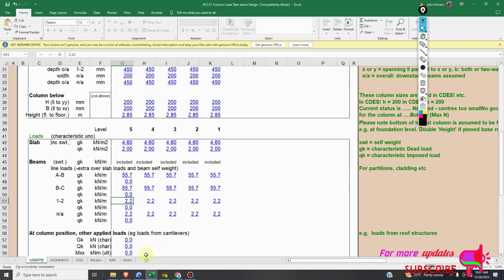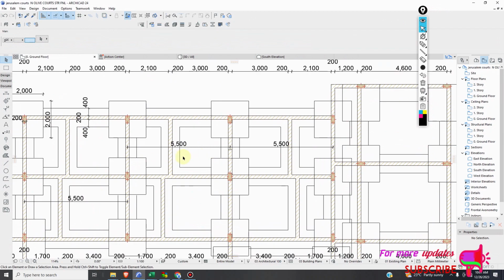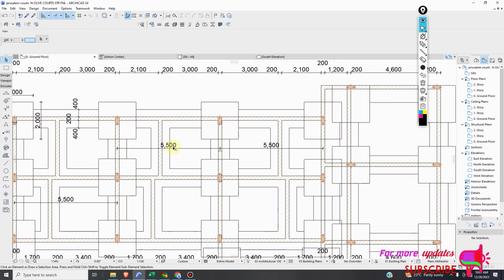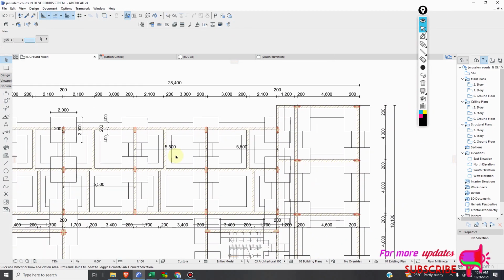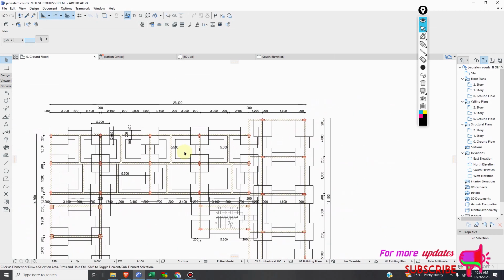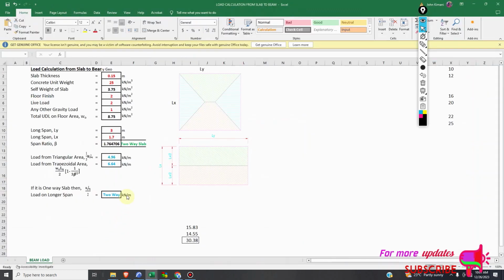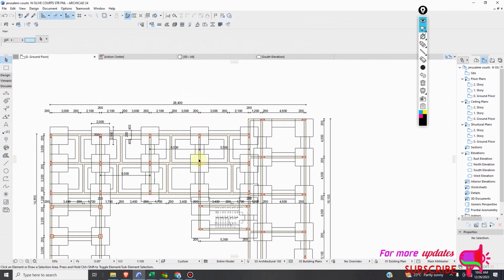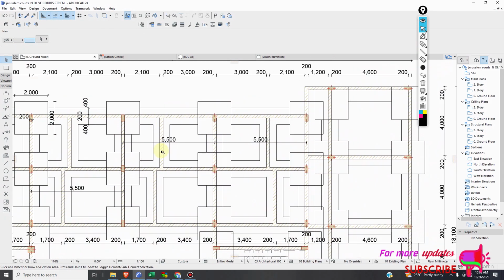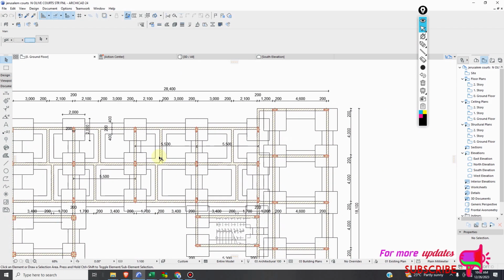So in the other direction we can still do the same. Now the direction will be load from this small panel. So we have 3 and 3. And then we got 8.75, right? So let's just do 3 and 3. Now the other beam will be its self-weight plus its partition load.